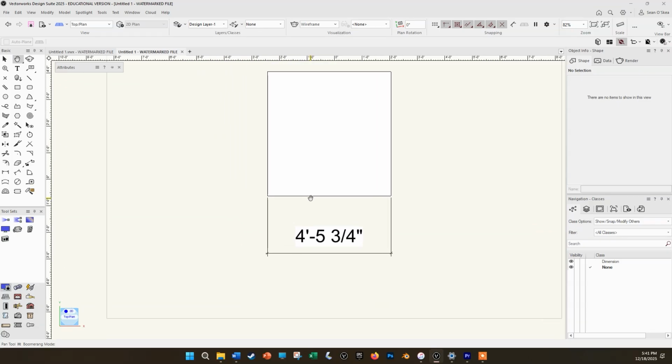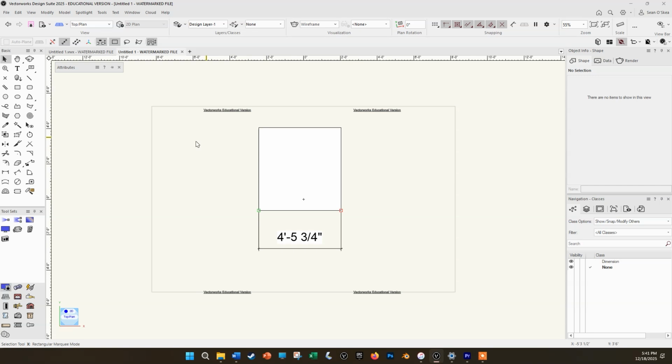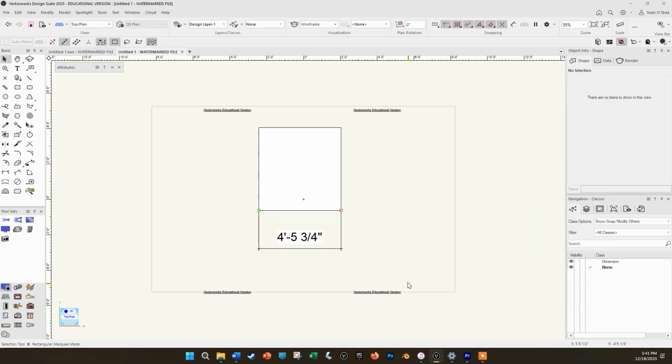And there are other navigational commands when we move into 3D, but for now, the scroll wheel and the spacebar will do most of what you need for 2D. And one last thing to keep an eye on, if you have a full-size keyboard with a 10-key number pad off on the side, that can be very handy for navigating in 3D, but if you have the number lock on and you accidentally bump one of those numbers, you might move into a 3D view.